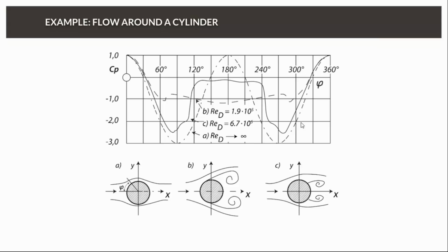And this is the theory where there would be no viscosity. So this you see in dotted line, and we call it like if the Reynolds number would be infinite. But unfortunately there's viscosity, so as soon as there is a positive pressure gradient, the boundary layer will suffer, and if the pressure gradient is too strong, the flow will separate.